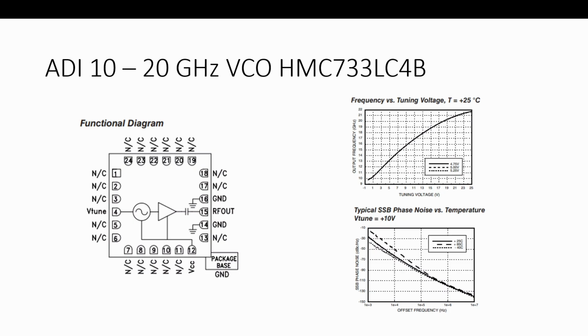And it would be really small. It would be 70 dB down. And then the higher frequency phase components are 80 dB or 90 dB, et cetera. So it's showing you components of each individual phase modulation that's occurring at it. And that's a method of evaluating the phase noise of this voltage controlled oscillator, VCO.